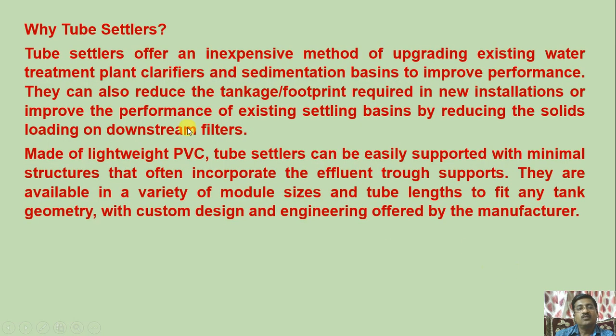Now why tube settlers again? So I will repeat the same. Tube settlers offer an inexpensive method of upgrading existing water treatment plant clarifiers and sedimentation basins to improve performance. They can also reduce the tankage or footprint required in new installations, or improve the performance of existing settling basins by reducing the solids loading on downstream filters.